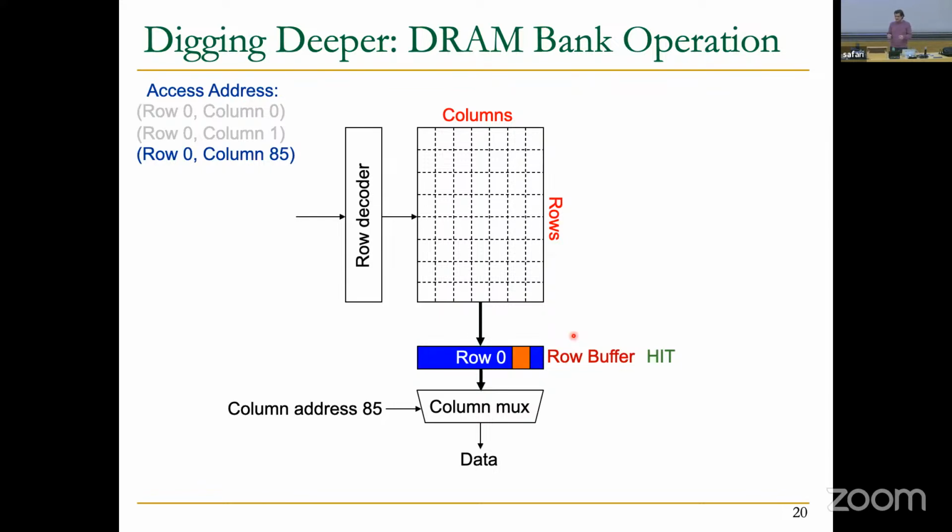So I will try to summarize your question. We have multiple banks, and we can start accesses in those multiple banks in consecutive cycles. But I've shown you here that two consecutive requests can be served from the same bank in consecutive cycles, right? Basically, you don't have bandwidth to serve another request that could go to a different bank. And at that point, as the memory controller, you have to make a decision. You need to either serve one request or do the other.